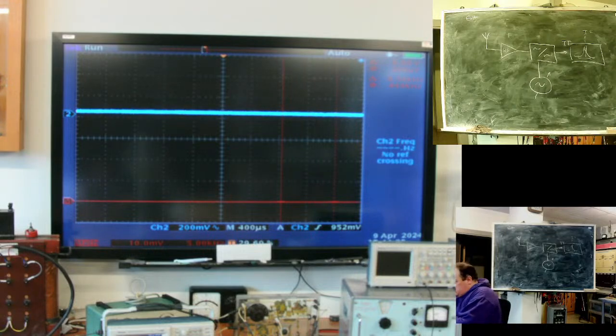And what does this give you? The ability to create the main signal processing path for one particular frequency. Only the input stage and converter are frequency variable. Most of your system will be frequency independent.